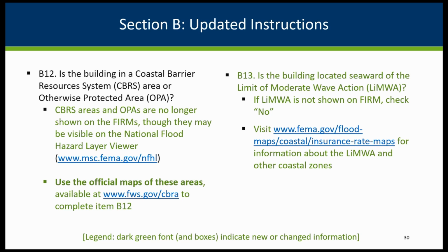Okay. And then lastly, for B13, the elevation certificate asks if you are located seaward of the limit of moderate wave action, or the LiMWA. If the LiMWA is not shown on the FIRM, check no. This is important because for St. Louis County, when those preliminary maps become effective, we will have coastal areas that will have a LiMWA in some instances located. So for St. Louis County, this will be relevant in the future. And every place else in the state, you can say no.